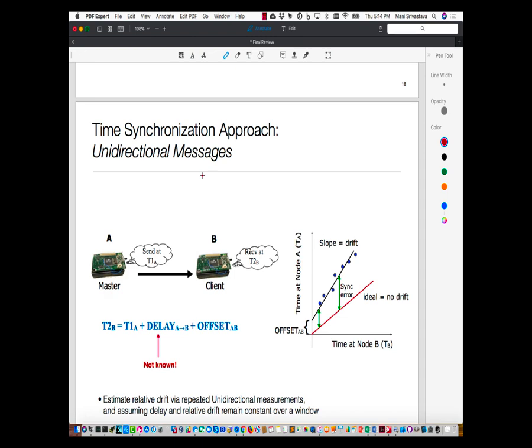And these clocks in Hexaware and Raspberry Pi are pretty good. They may drift, let's say, 50 microseconds a second relative to each other. I would be pleasantly happy if you are in the millisecond territory, millisecond to 10 milliseconds at the pin level, and visual synchronization at the display level.